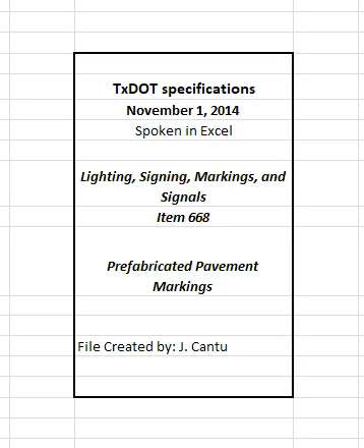Place pavement markings in alignment with the guides without deviating from the alignment more than 1 inch per 200 feet of roadway or more than 2 inches maximum and with no abrupt deviations. 3.2 Placement limitations. Do not place Type B pavement marking materials between September 30th and March 1st unless otherwise directed.